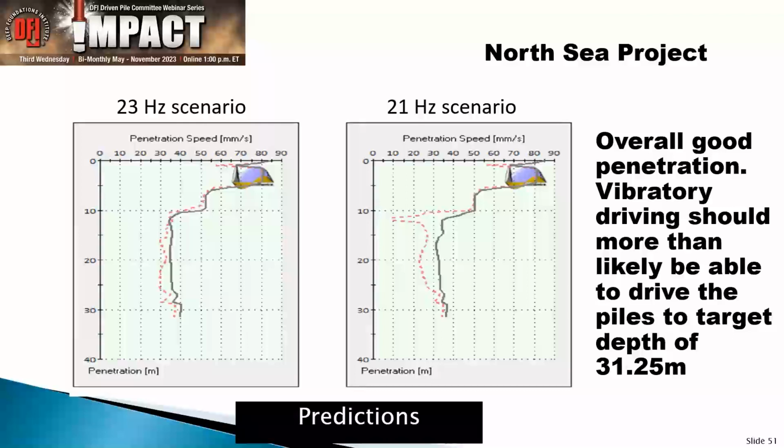Go one step further. We did a project a couple of years ago in northern Finland, where we knew that we could not get the piles into the ground with a vibratory hammer. What we did there, we lowered explosives onto the seabed and blasted the whole thing to create granular soils out of rock.